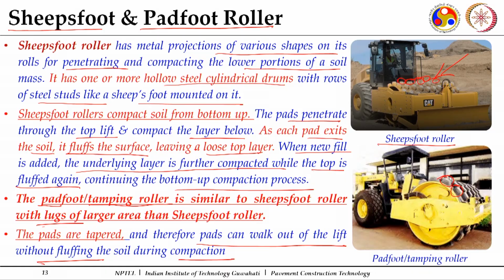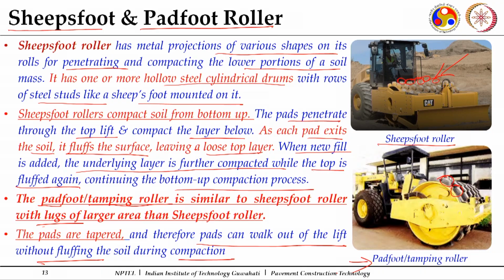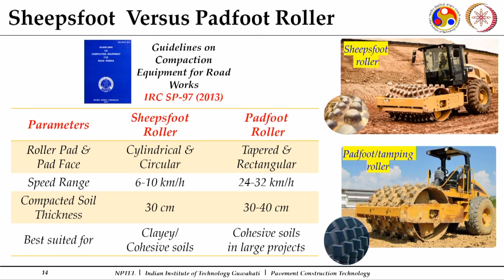So that helps us achieve good compaction, because there is no fluffing, or less fluffing, in the top portion when we are using the pad foot rollers, which we also call tamping rollers.